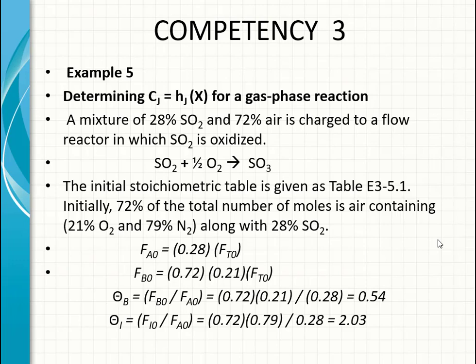And FB0, which is oxygen, is going to be 0.72, which is the percent of air, but of that 0.72, 0.21 is oxygen, so it's going to be 0.72 times 0.21 times FT0, the total molar flow rate initially.